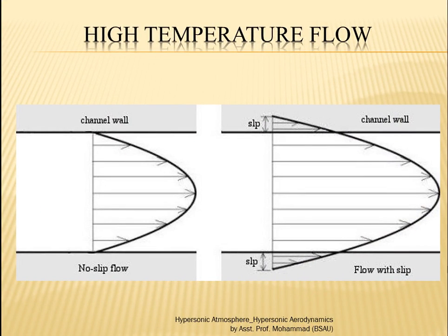Now the immediate consequence of this low density flow is that the most favorite and vital concept we have been seeing till now, the no slip condition, is no longer valid. So on the wall we don't get zero velocity, the fluid starts slipping there, so we have some kind of extra velocity available here. This is the pipe flow, or the flow between two plates.